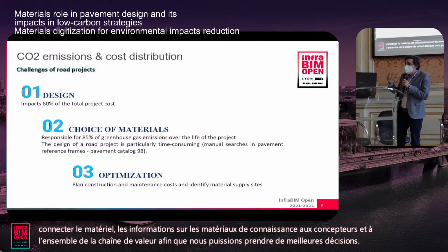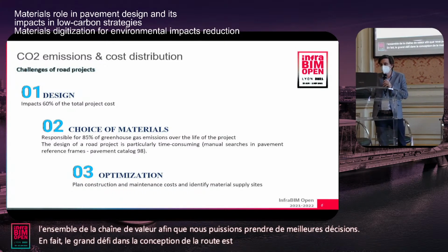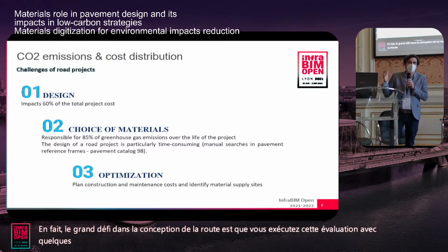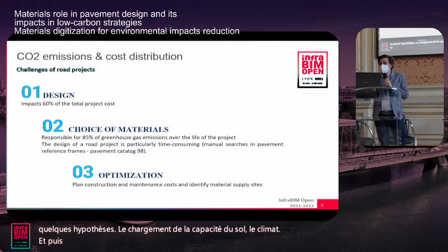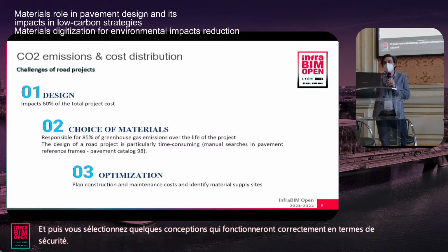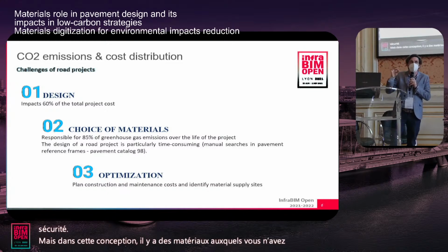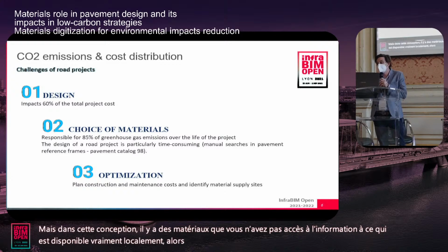In fact, the big challenge in designing the road is that you run this assessment with a few assumptions. You know the loading, you know the soil capacity, the climate, and then you select a few designs that will perform adequately in terms of safety. But within this design, there are materials that you don't have access to the information on what is available really locally. So you take these materials, you run the assessment.